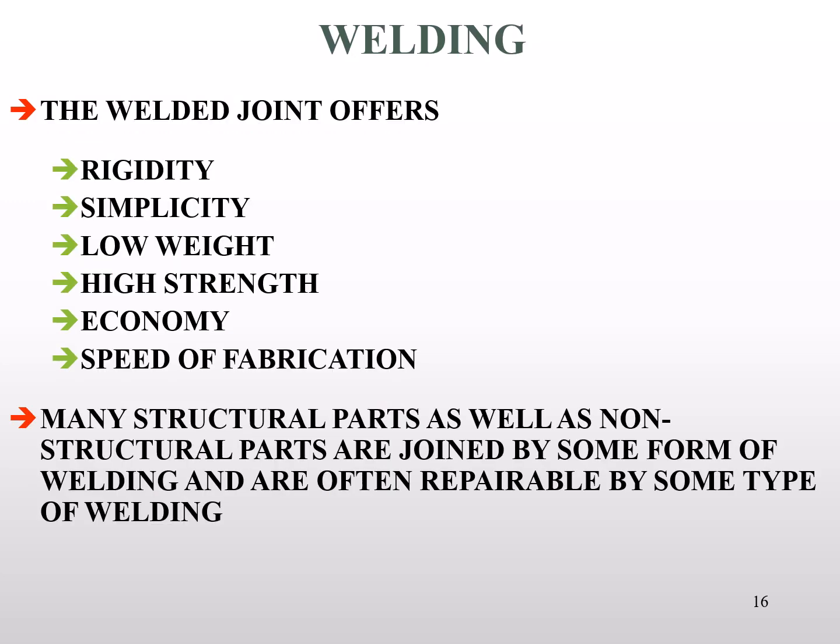So the question may be, why do we choose to weld a joint? Because it takes equipment and skill levels not typically found with every mechanic. Well, here is your list of answers. Rigidity. A welded joint is a very strong joint. Simplicity. Welded joints require less machining, less hole drilling, less time to fabricate. Welded joints can be very low weight. The amount of steel used to make a weld can weigh a lot less than hardware might.